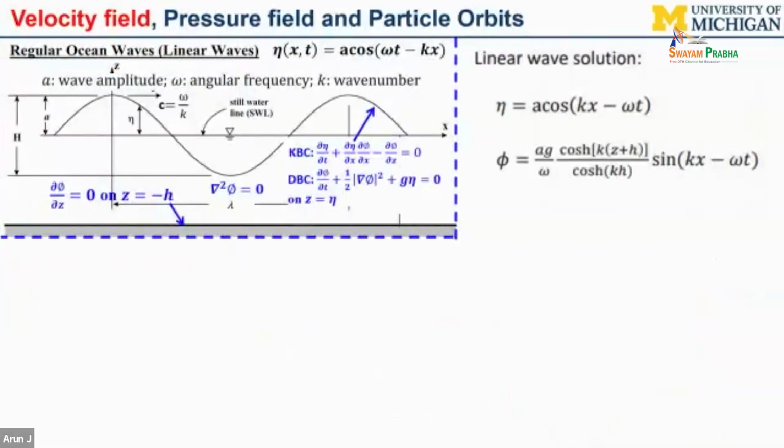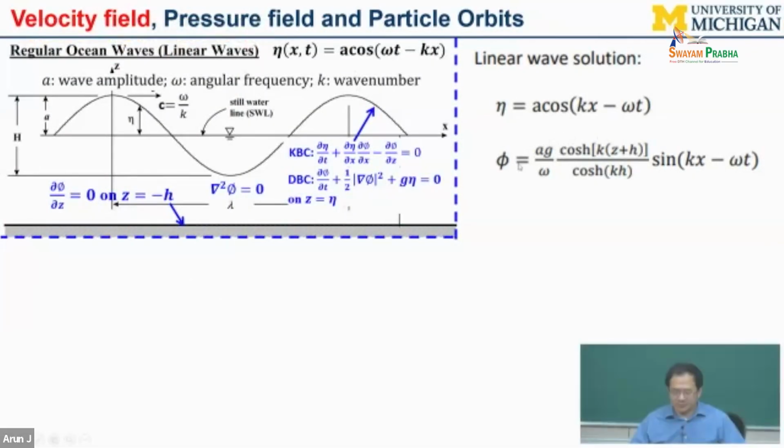So now you already get this potential flow function, right? We skip the mathematical derivation of how to get this. The principle is the potential function plus a boundary condition. You simplify that. If you know the surface function A, then the potential function you can get this way.